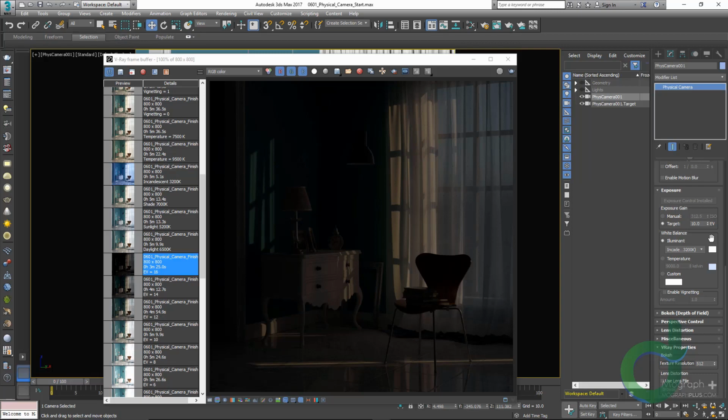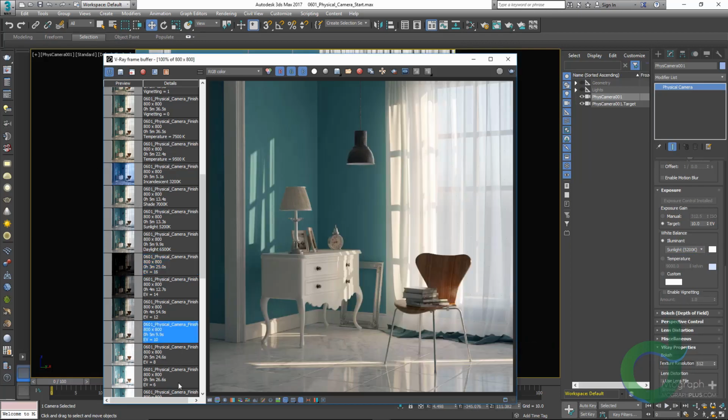If you are in natural daylight lighting, you can set the preset to a neutral daylight 6500 K. If you are under very hot warm sunlight and there is some yellow color cast in the scene, you can use the sunlight 5200 K preset to make the whites white again by casting out the yellow color produced by the light source. If I go to the frame buffer and load the render with EV set to 10 and also enable my correction tools and enable white balance,